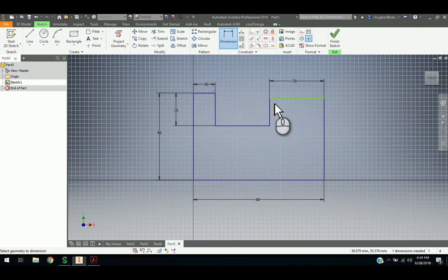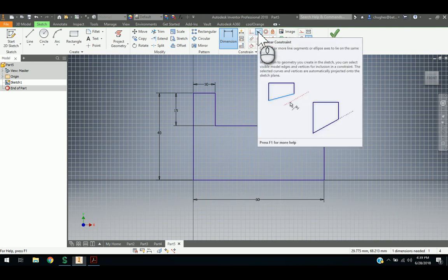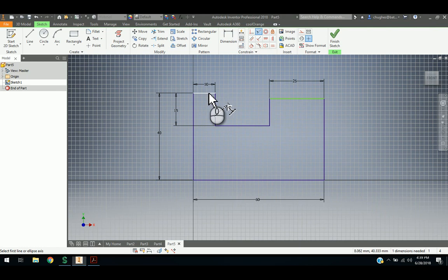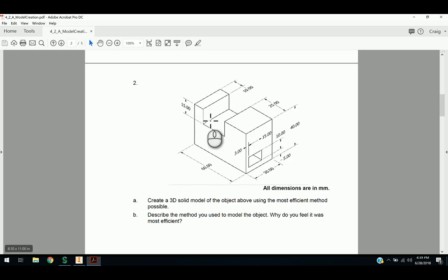Now in this case these two lines are not aligned together anymore, which can sometimes happen when you trim a sketch. I'm going to use a geometric constraint, the collinear constraint. If I click on collinear, choose this line and choose this line, it will set those on the same line or the same path, so they are in line together. You'll notice this line turned purple again, indicating that it is fully constrained. That finishes out the front profile of the sketch. The only thing we're going to have to do is extrude and then cut this square hole through the part. So finish the sketch.